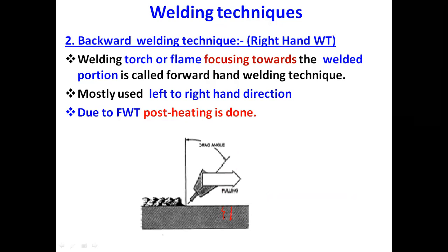The second defect is cavities. Porosity is present due to entrapped gas during solidification. The voids are spherical or elongated, and the shrinkage voids are due to shrinkage during solidification. That means some gap or cavity is created.